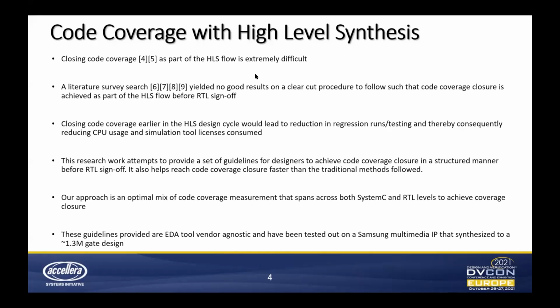This approach is an optimal mix of code coverage measurement that spans both SystemC and RTL levels to achieve coverage closure. These guidelines are EDA tool vendor agnostic and have been tested on a Samsung multimedia IP design that synthesizes to about 1.3 million gates.